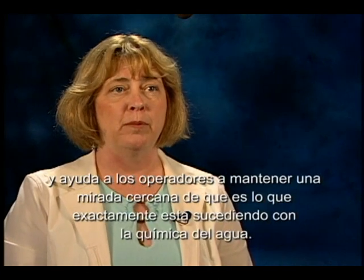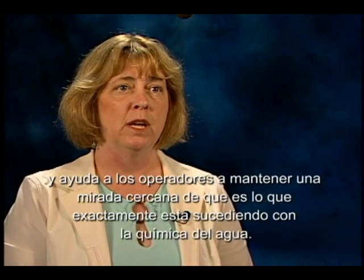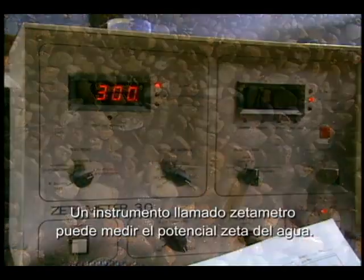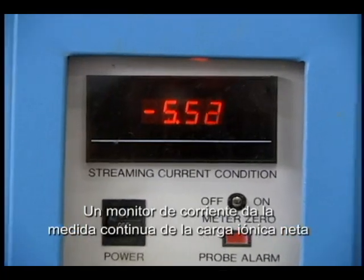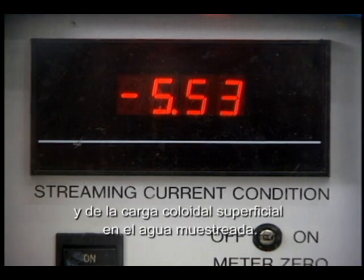And what that helps operators to do is to keep a very close watch of exactly what's going on with the water chemistry. Sending the effluent through a small pilot filter can test the filterability of the settled water. An instrument called a zeta meter can test the zeta potential of the water. A streaming current monitor gives a continuous readout of the net ionic and colloidal surface charge in sample water.